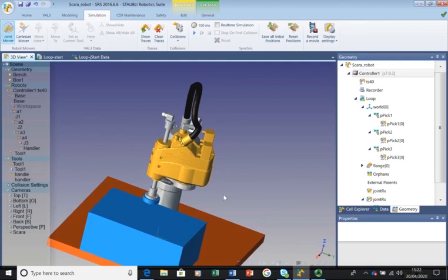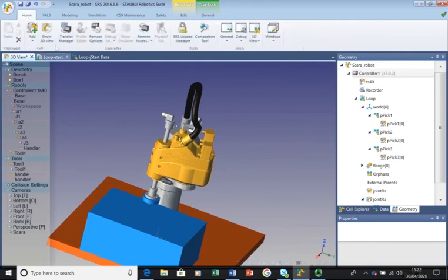Once we were happy with this code, we would go to the transfer manager and transfer this Val3 code to the actual robot. Depending on how confident you were that you picked P.1, 2, and 3, etc., exactly the same as a real-world environment, you could just run it. I wouldn't recommend doing that. I would send it to the robot and then reteach the real-world positions of P.1, 2, 3, and J start, and then run the program.